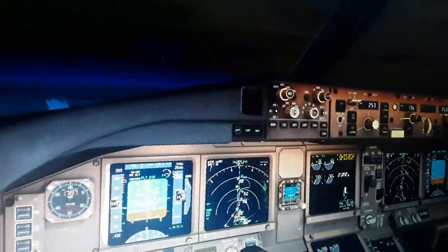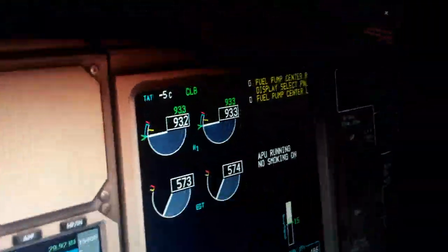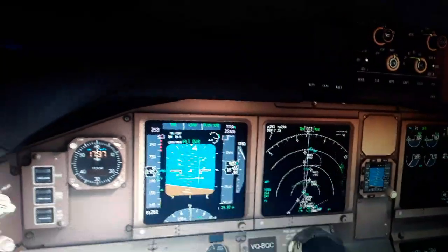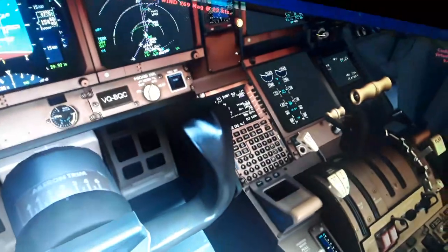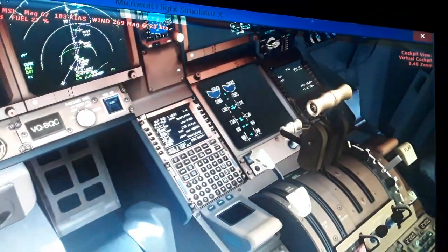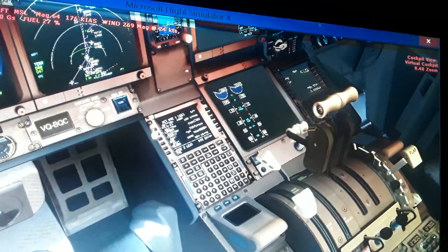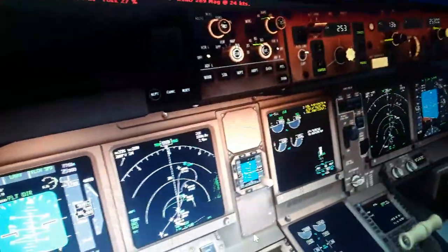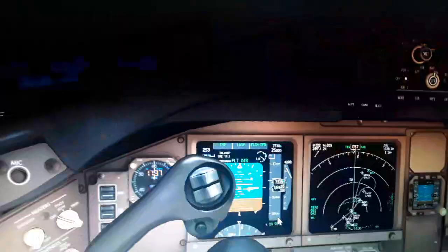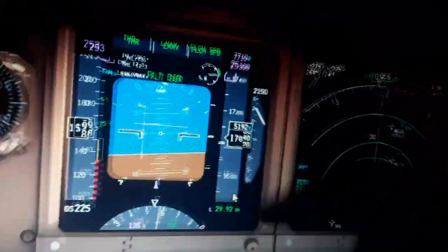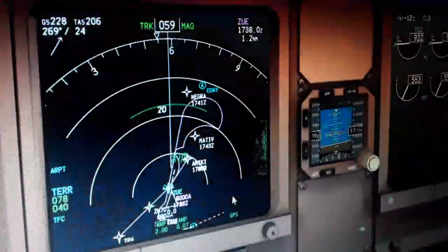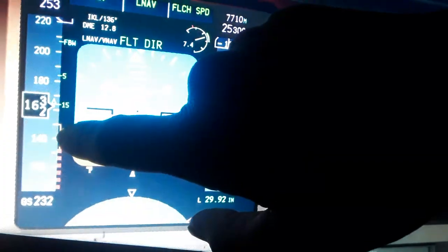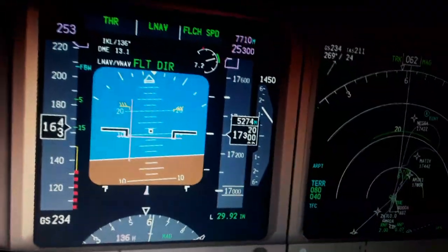You can see the thrust here, commanded by the flight computer and the autothrottle system, and it transfers a couple of waypoints here. Pitch down a little bit, avoid the stall. The warning here has the yellow and the red. So you can see also how fast we climb with a small rate of climb right now, because we are close to the stall speed, we need to avoid this.